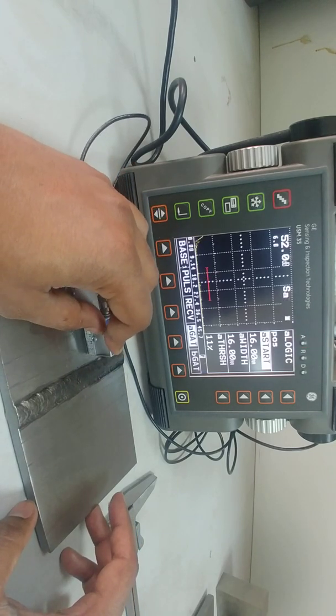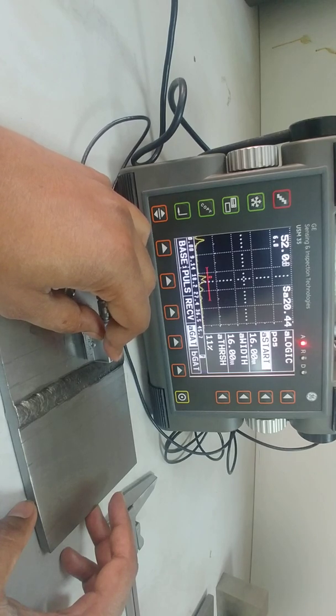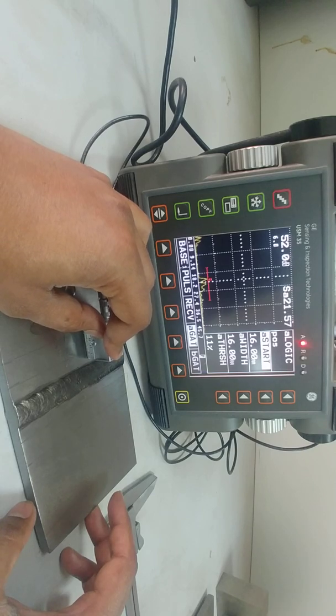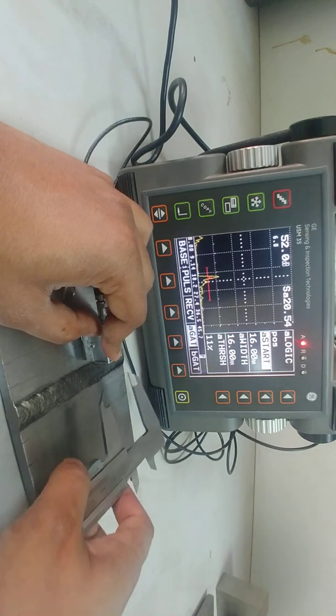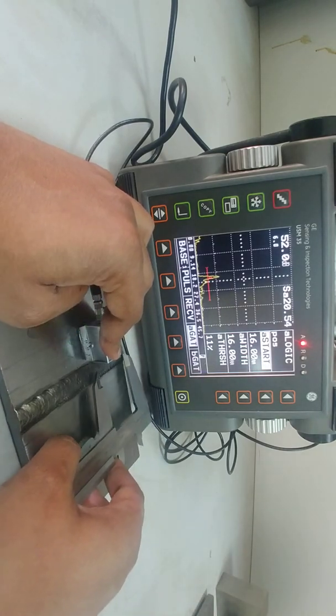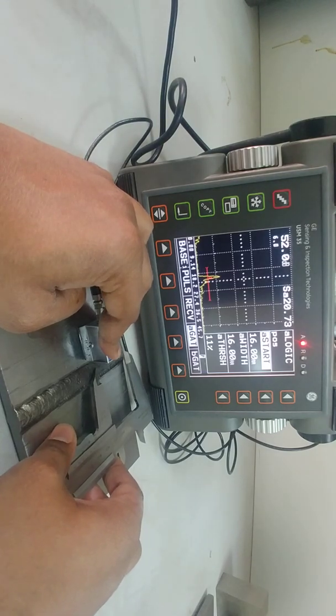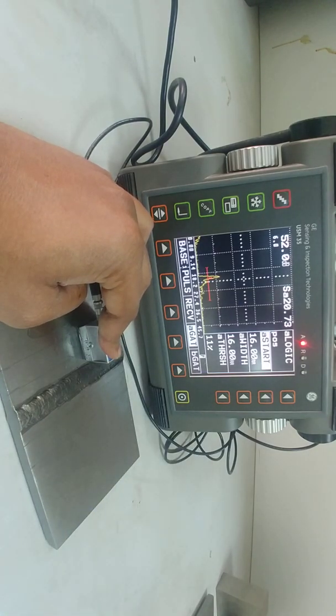And you can even get the point where you're getting the defect. So you have to measure everything, all the details. So at what point I'm getting it? If I take the top side as my reference axis, so I'm getting this defect at 34 mm from the top side. From top side 34 mm. Later on we'll be using this one to make a report.